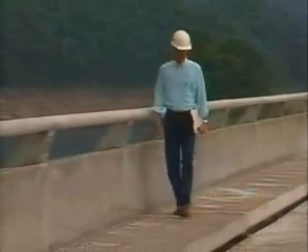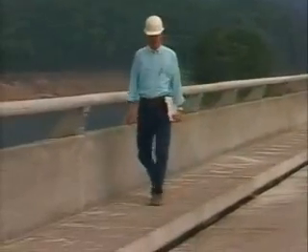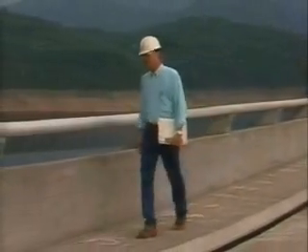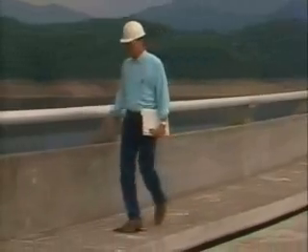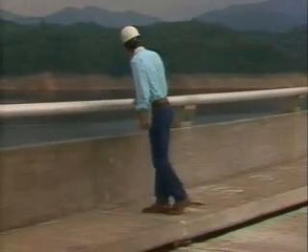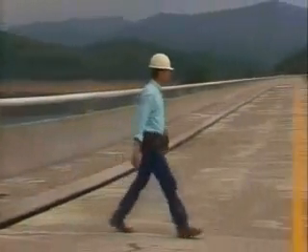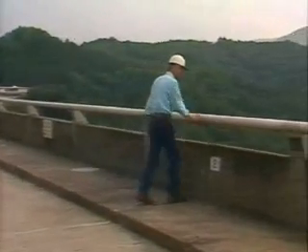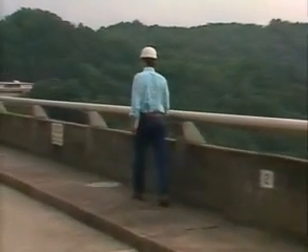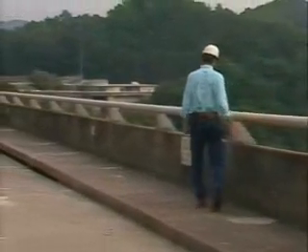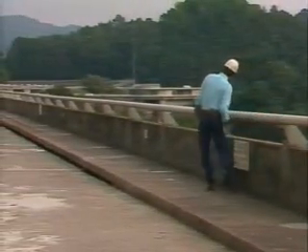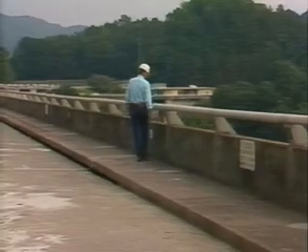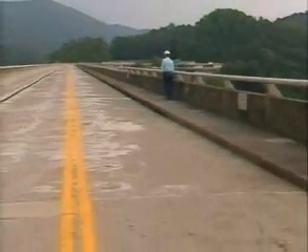When inspecting the crest, remember to systematically walk its length. One technique for achieving thorough coverage is to walk along one side of the crest. Then cross over, and walk along the other side. Walking the crest gives you the opportunity to inspect the crest closely. Walking the crest also gives you an opportunity to get an overall picture of the condition of other features of the dam.